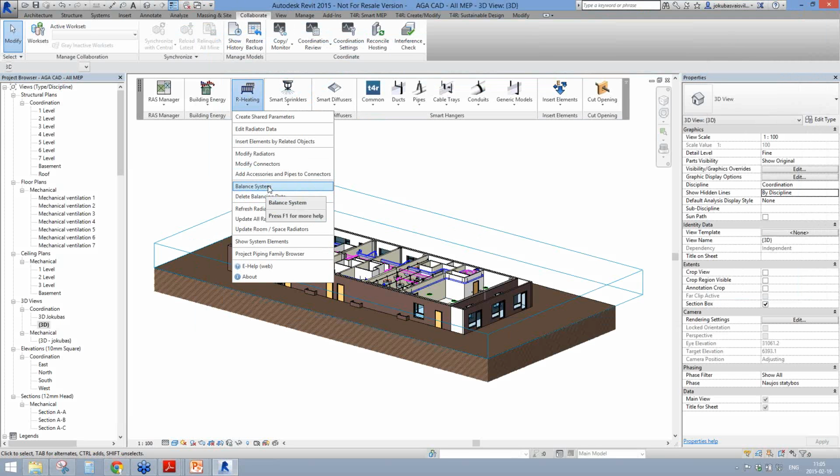This is the only one that we have for pipes and for pressure drop calculation. The result after balancing the system is the KV value. That means on each of the balancing valves you will have a KV value that will vary from 1 to 7, I think so.